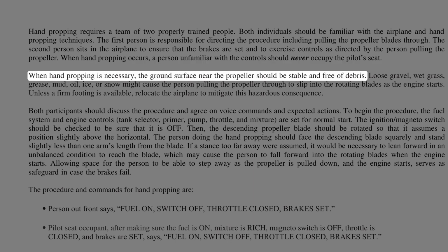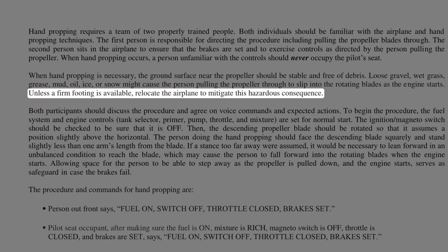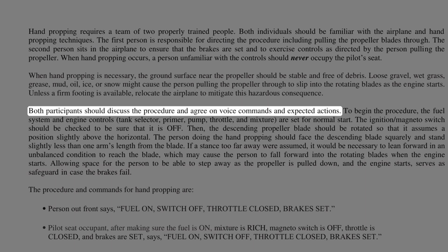When hand-propping is necessary, the ground surface near the propeller should be stable and free of debris. Loose gravel, wet grass, grease, mud, oil, ice, or snow might cause the person pulling the propeller through to slip into the rotating blades as the engine starts. Unless a firm footing is available, relocate the airplane to mitigate this hazardous consequence. Both participants should discuss the procedure and agree on voice commands and expected actions.